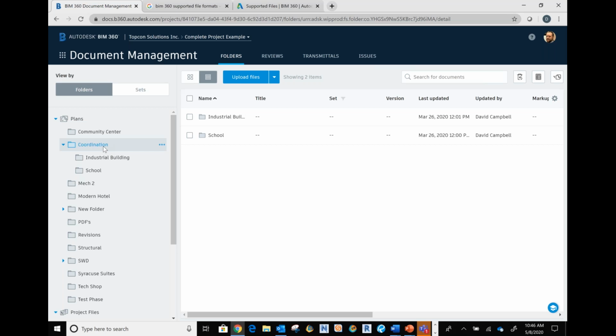So if I want to clash, let's say I have a 13-story hotel building, and I want to clash each level, or even clash underground, I want to know where my pipes are going when they come up into my model. If I have my penetration holes set correctly, my stub ups are right. Make sure I'm not going into any walls or any supports. I'm not going to try to go up through a beam.